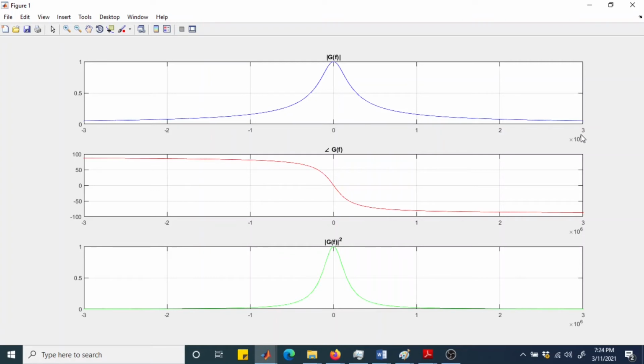But since we are considering the low pass filter, you can observe that there is a constant decay. So there is always a distortion. Or in terms of phase, you can observe initially there is a certain region where it seems to be a little bit linear at low frequency, and then we have a non-linearity, right? So we are indeed interested in this range, where the phase is linear and the magnitude is as linear as possible.